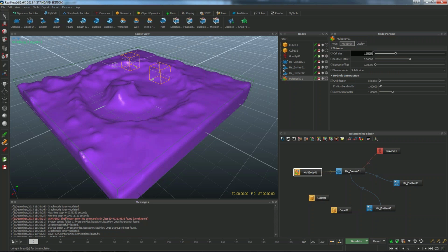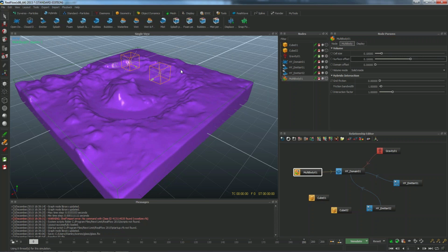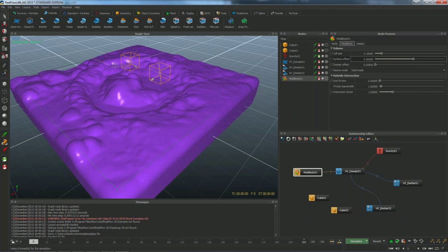The solution for that is, for example, I'm going to put 0.1 here, and if I put a surface offset, maybe with this value, you see that the isosurface for this geometry has grown a bit. So I'm going to set 5, for example. With the thinnest geometry, you will need to use the surface offset for sure.